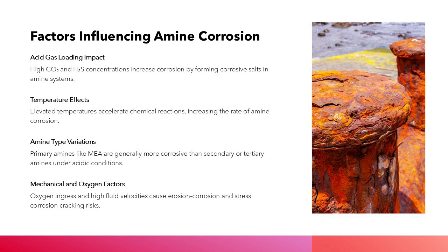Oxygen ingress is another critical factor, as even small amounts can drastically increase corrosion rates, particularly with MEA. Mechanical factors like high fluid velocities contribute to erosion corrosion, while high-stress areas such as welds and heat-affected zones are vulnerable to stress corrosion cracking. These factors often act synergistically, making corrosion control a complex challenge.